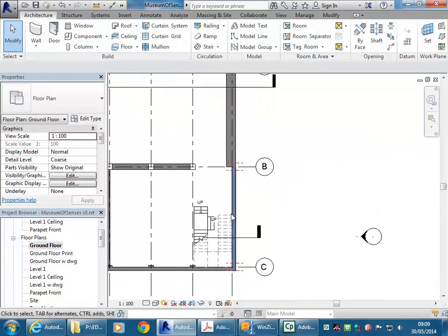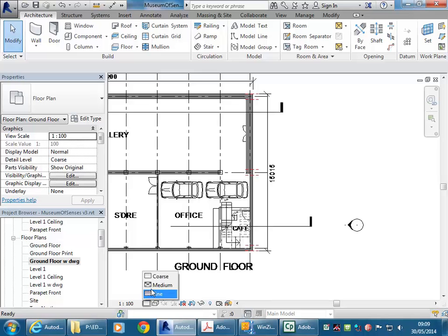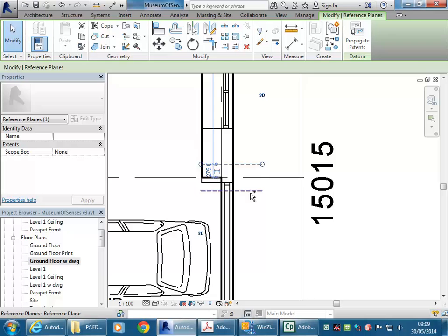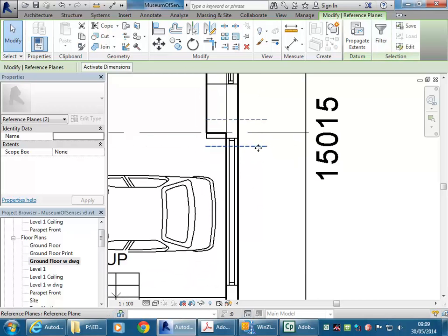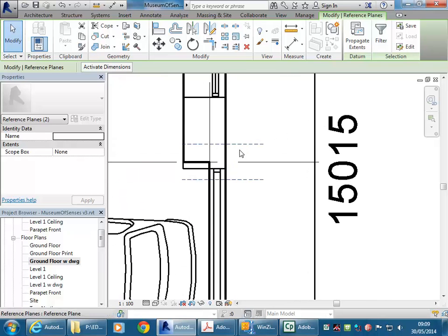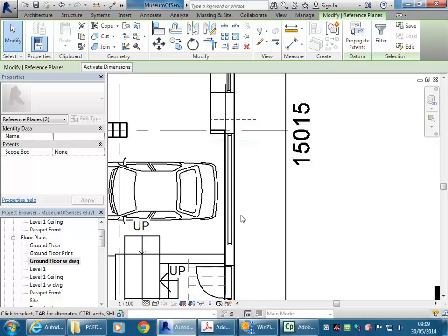And then we've got a pier somewhere here. So to work that out, if you have a look at the image that's inserted, you can use that as a guide. But you can see already that there must be something wrong with this plan, because there is a big pier there and they've shown this door going into it. So again, you're going to need to use your judgment, have a look at the photo and use that as a reference rather than just the drawings.